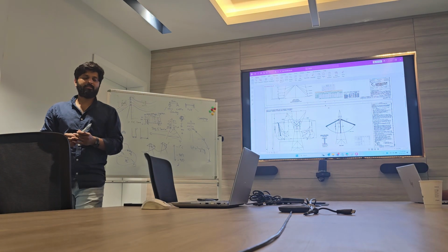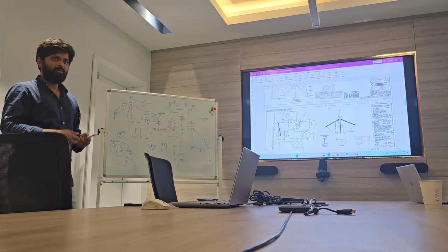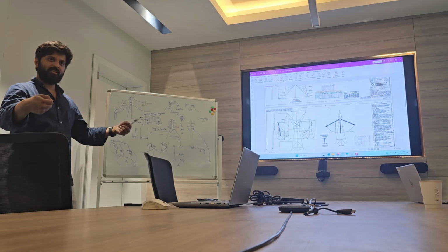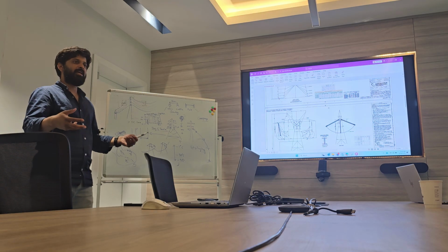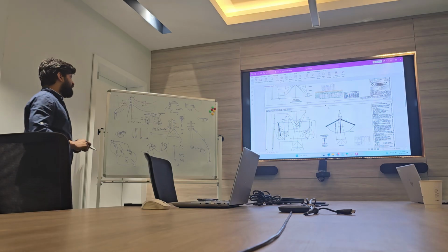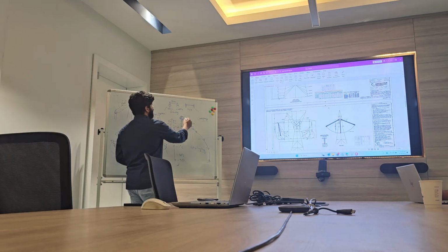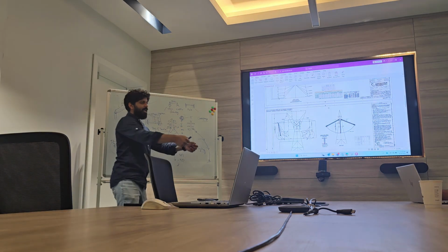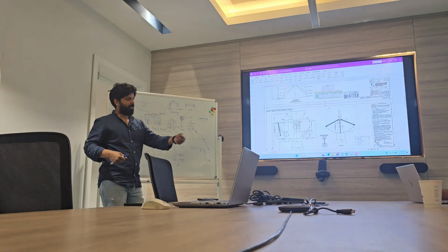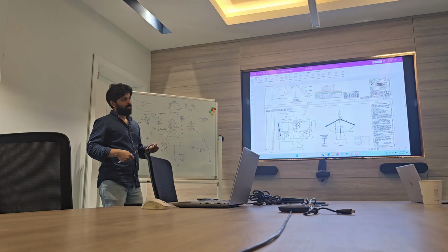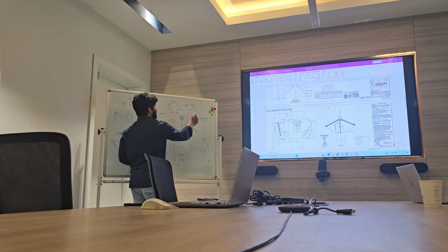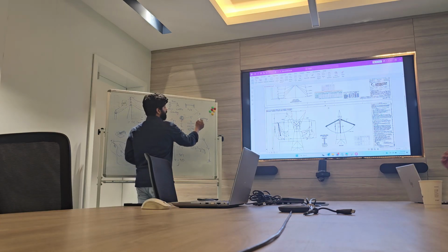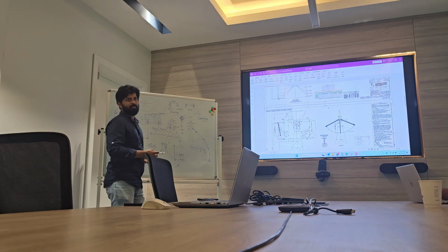Yeah. Sag, as I told you, even if you have a conductor, when you let it relax, it will sag. So there is something called conductor tension capacity. Meaning I pull the conductor, I tie it somewhere, I pull it. After some time it will break. That is called ultimate tensile strength of the conductor, UTS.